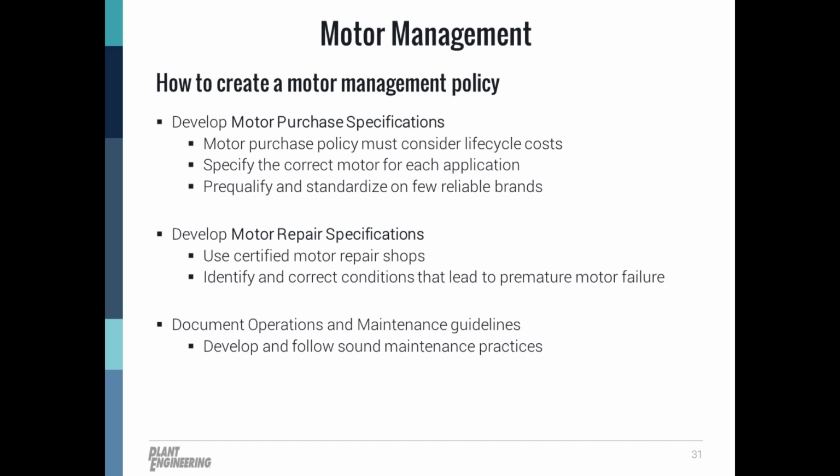All right, operations and maintenance. Ronnie covered a lot of that stuff earlier. Routine maintenance on the motors. Focus more time on critical motors, motors with high usage rates, motors that are over 4,000 to 5,000 run hours per year. And then the last component, motor repair.